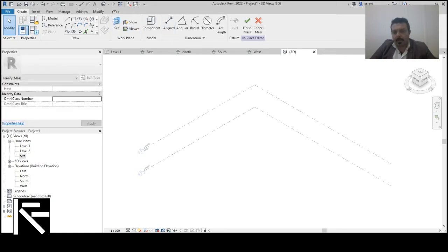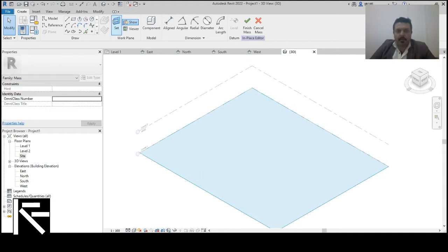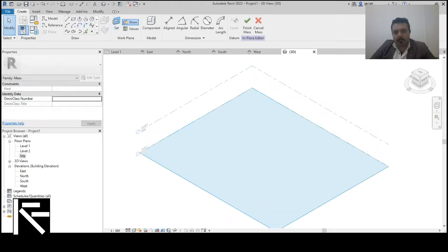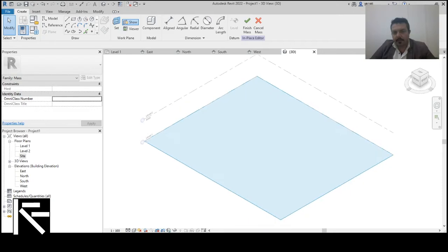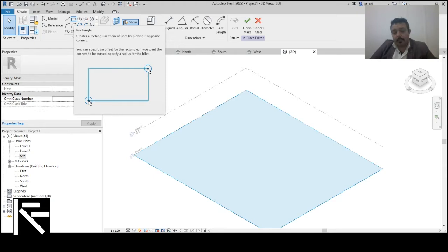Let's start to check what this workplace is. If I show the workplace, level 1 becomes bold. It means that I am starting to develop something there. But if I change the set, I am able to shift between my workplaces, either to the second level or the first level. Let's go back to level 1. Now it is shown, and try to keep it shown while you are working in a specific area. Otherwise, if it is not set, you will draw wrongly.